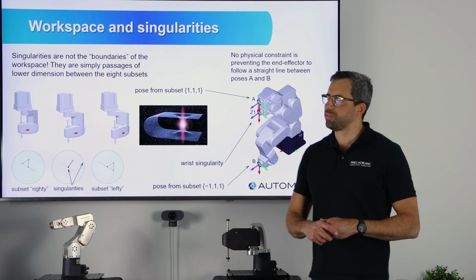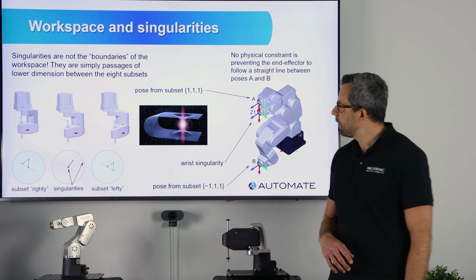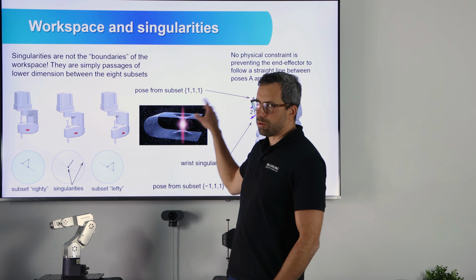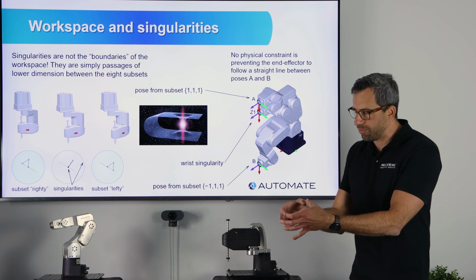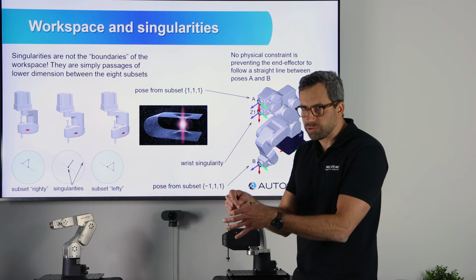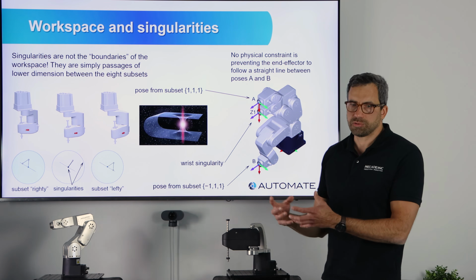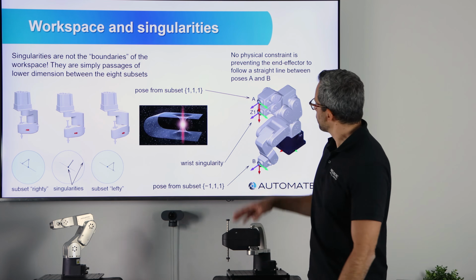And okay, somebody will say, well, with SCARA robots, we don't follow lines, we just do pick and place in joint mode. It's the same. I will show you, it's not optimal. So even though you think, oh, I'm here, I need to go here, it's very close, it's inside the workspace, it will take you a lot of time. So it's not an optimal trajectory.